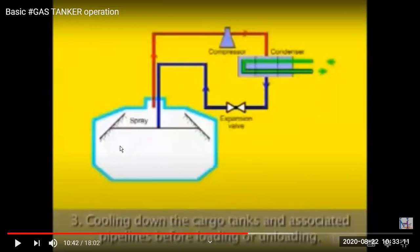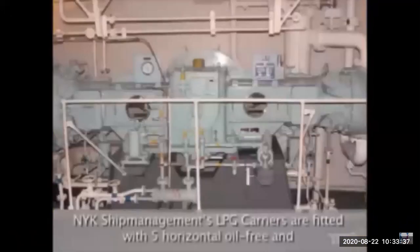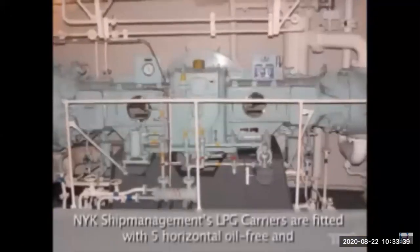So during cooling down, cargo is sprayed from the deck tank, or we keep some spare cargo every time in the deck tank, or if not, then we take from the shore and we spray in the cargo line. So again, there will be a lot of vapors. Same, it will be compressed, condensed, and expanded, and temperature is controlled. Pressure is also controlled, and all the pipelines are also cooled down.